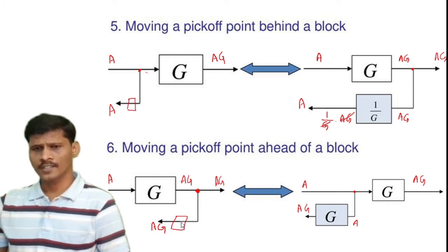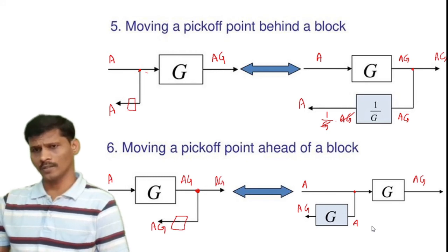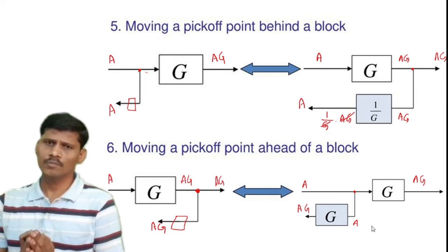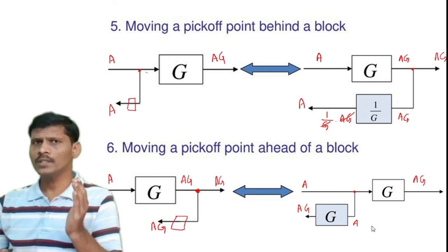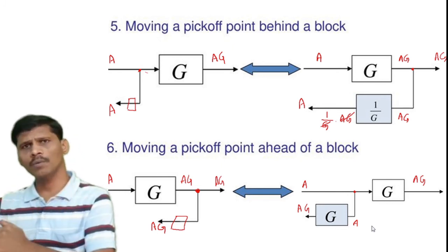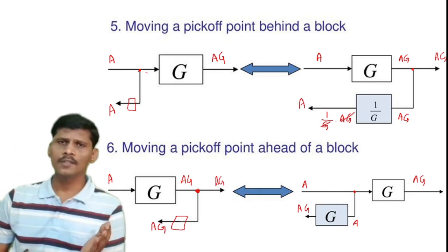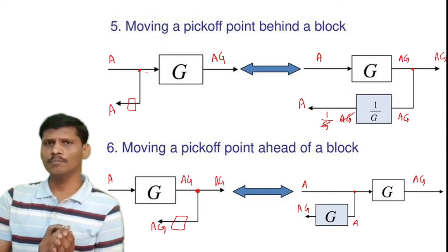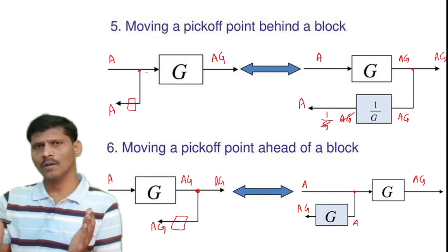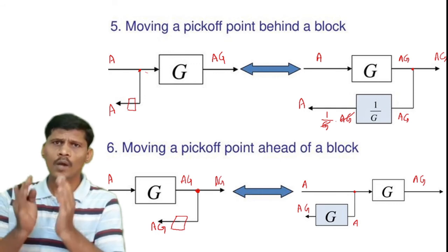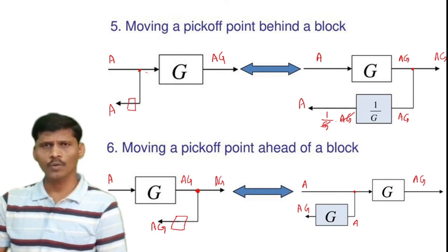Here consider another additional block, that is this one. So we keep in mind, moving the branch point before the block or after the block, or moving the summing point before the block or after the block. So consider one more additional block.